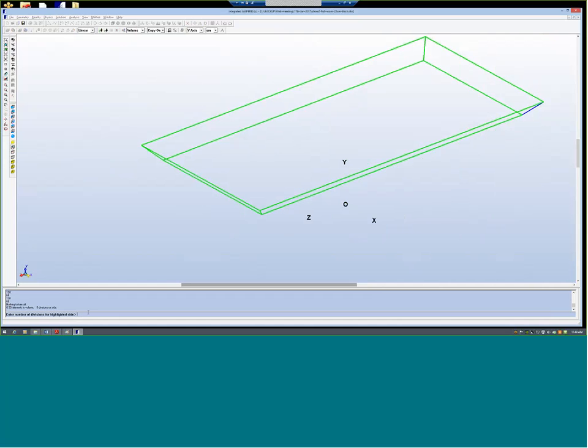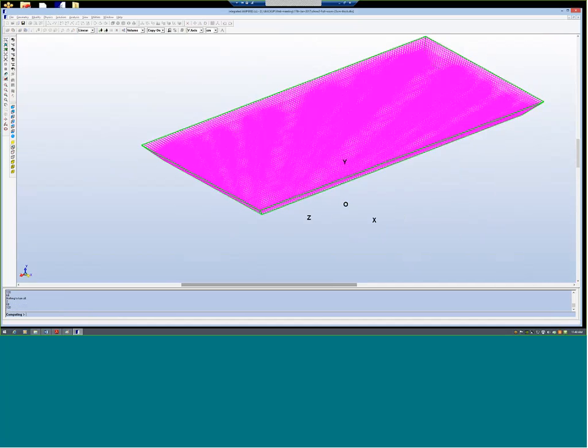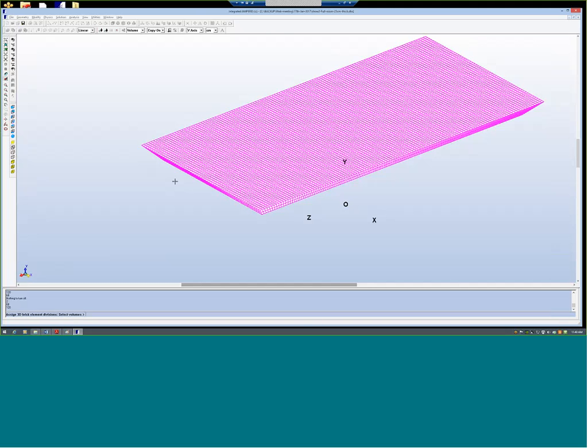I want to divide it into 2 parts there. Now this one I want to divide into 60 parts, and this is 120 parts. Exactly, I'm trying to match with whatever elements I used on the surface mesh. Same divisions on the surface. I'm taking it so that on the surface of the volume, the 2D elements and 3D elements will match. It is not necessary but recommended.